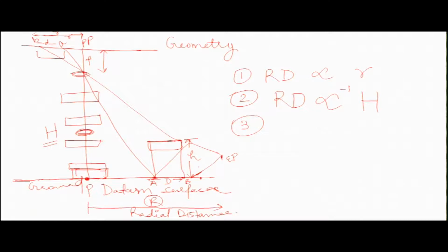So what it means? As this small h increases, relief displacement will also increase, because the taller the building, the larger area on the photograph it will cover. Okay, you understand here. So we got to know from here that relief displacement is also directly proportional to your small h.